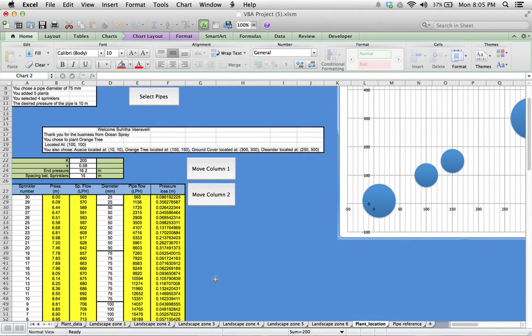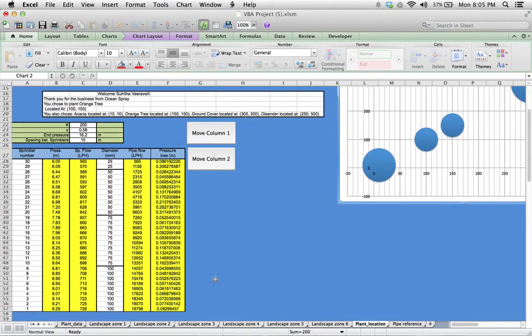So we imported some data from Chapter 3 Irrigation Simulation, as you can see here in the bottom corner, and we looked at mainly pressure and pipe flow in liters per hour. This separates out the data into the 4 different options for pipe sizes: the 25 millimeter diameter, 50 millimeter diameter, 75 millimeter diameter, and 100 millimeter diameter.